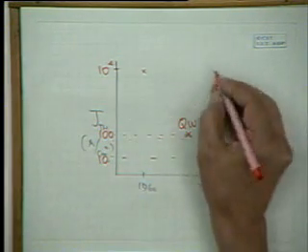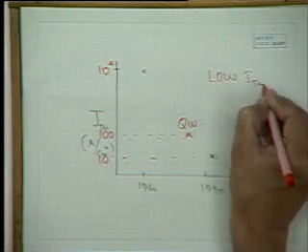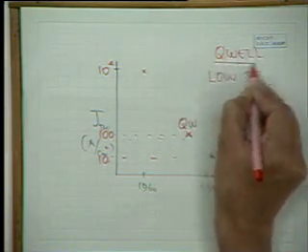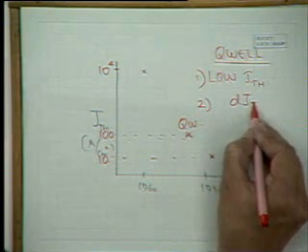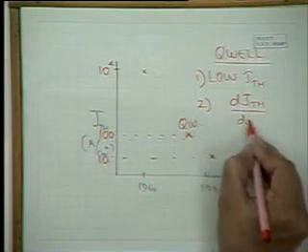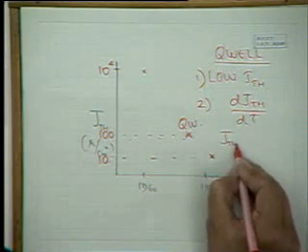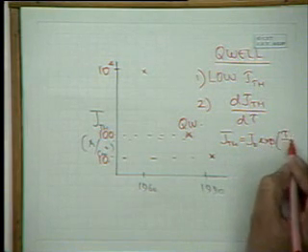So overall, quantum well lasers not only have lower JTH, they have lower dJTH/dT, which is very good for systems. We know that, for example, JTH is equal to J0 exponential T by T0.